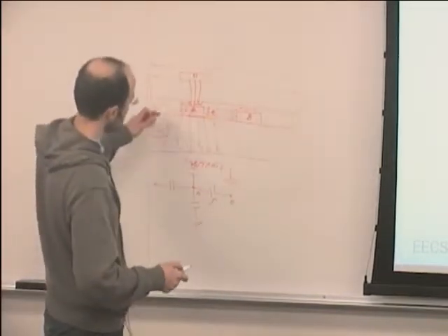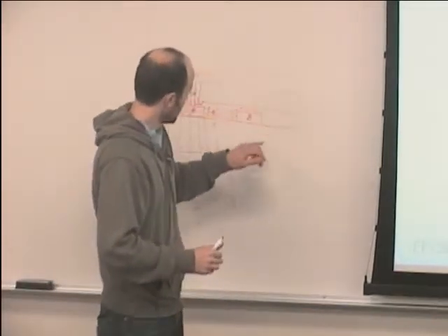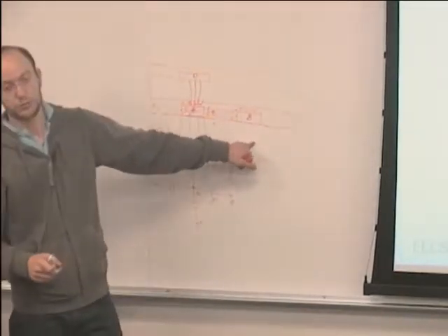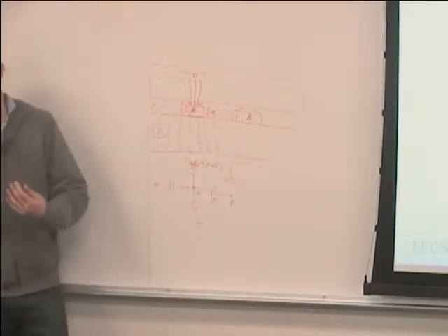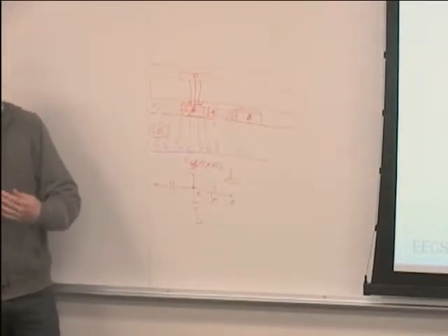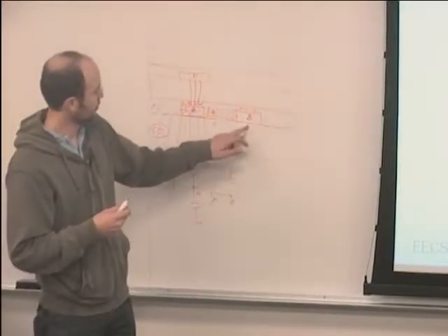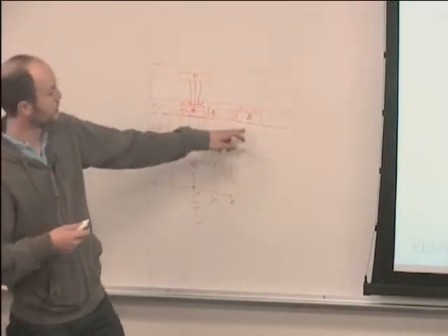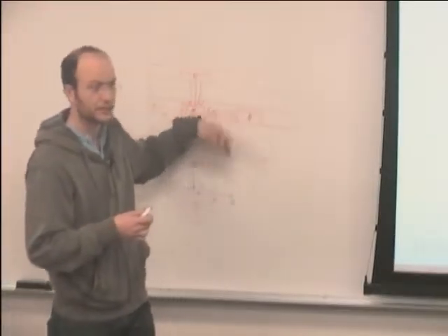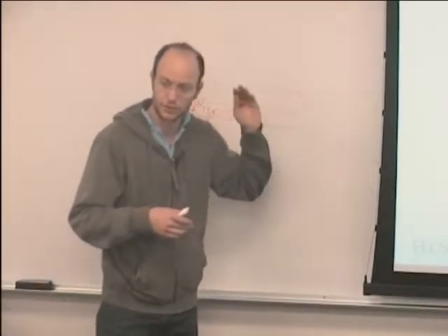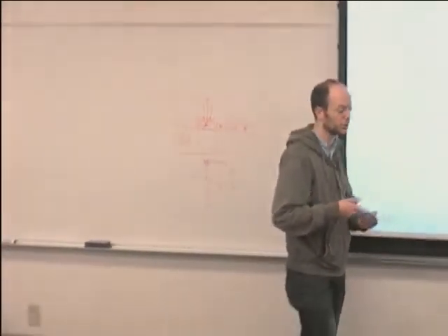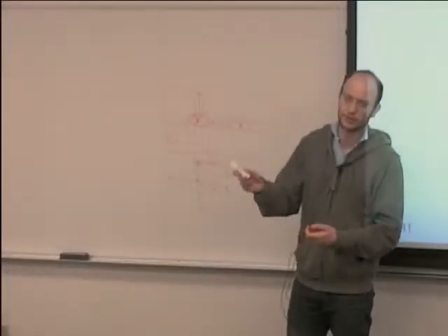So you should be able to do this. See, it's important that you can do it by hand so that you have some way to predict things. But it's also important to know that there are tools that extract these capacitors, that your parasitic extraction tool will do it. And the reason for that is that this geometry gets complicated very quickly, okay?